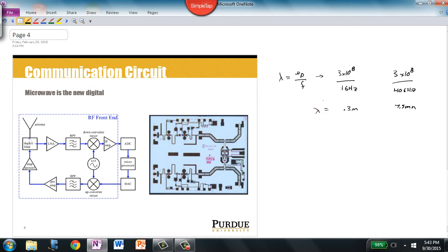You'll recall that the cutoff for when we have to apply electromagnetic analysis is lambda over 10 or lambda over 20, depending on which rule of thumb you like to apply. So divide that by 20, and you get 15 millimeters trace length as the cutoff for the low end, and at the high end frequencies, the 40 gigahertz frequencies, the cutoff is 0.375 millimeters.